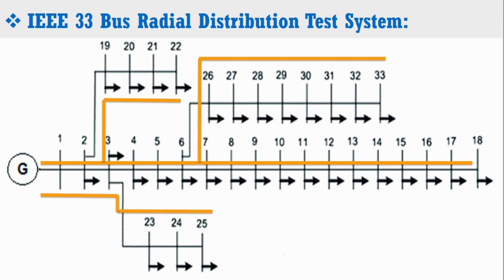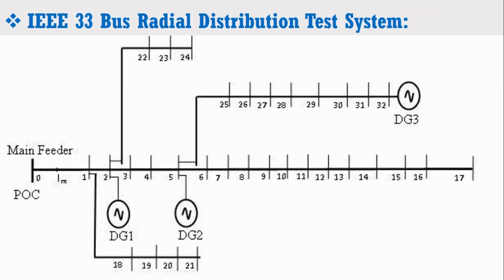Now due to the latest advancement in renewable technology such as solar, wind energy, it is now possible to supply the increased load demand by using the distributed generation resources. In this way, the DG is connected to that location which has the higher load demand. By using this method, the cost of the transmission as well as losses are significantly reduced.